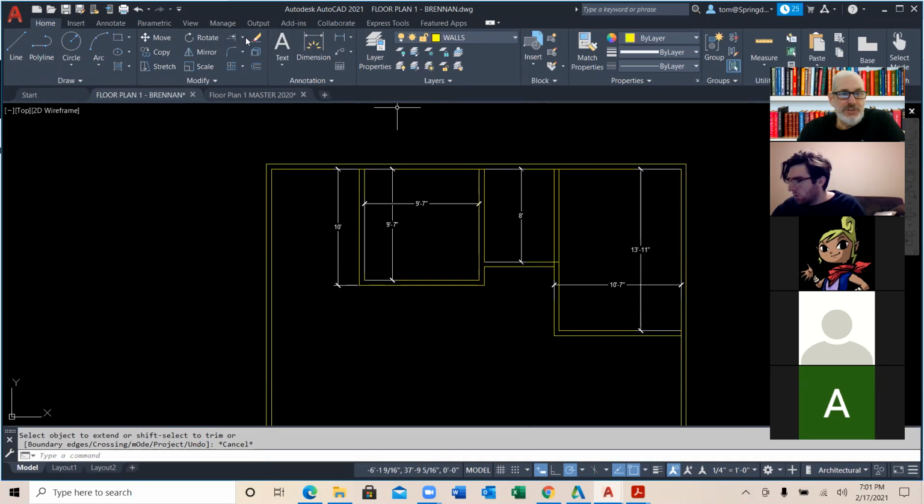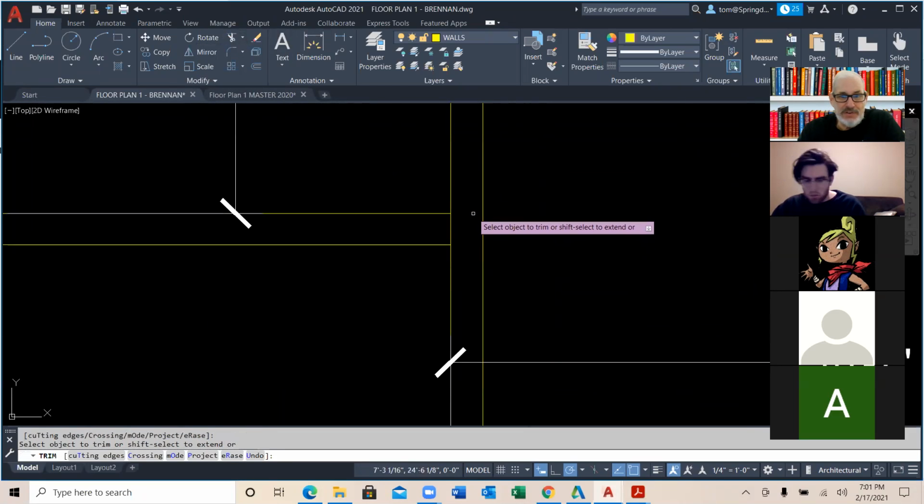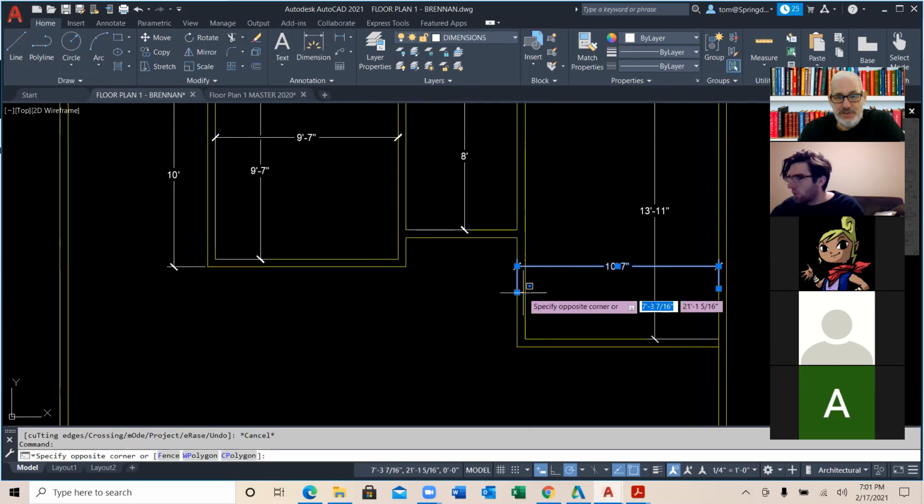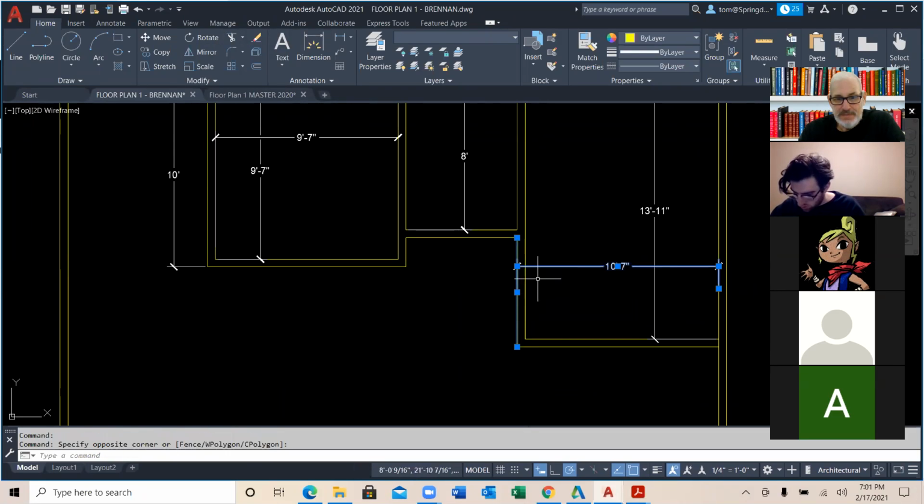And then I just use trim, and trim and extend, again, they share the same location here. We just go here and get rid of these little things that we have there. And we finally do this. Does that answer your question there? Yeah. Okay. Extend will automatically just go up to the next line. Yep. By default it will automatically, you can specify where you want the boundary to be, but by default it's just going to go to the next logical line that would stop it. Okay, that's all it's going to do right there. You guys hold up okay?